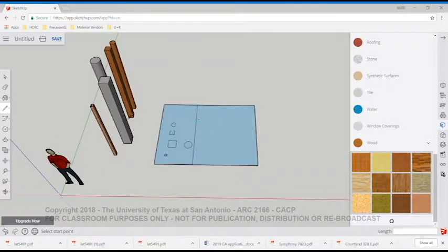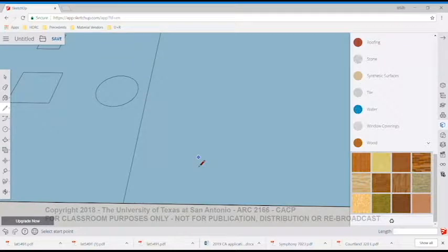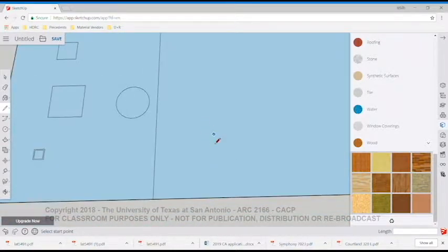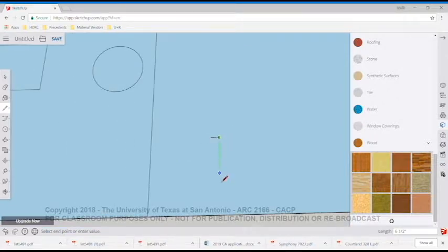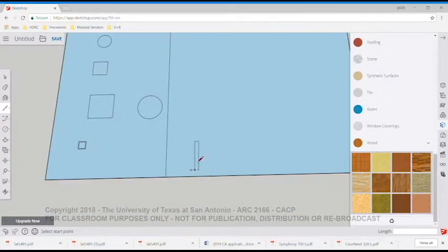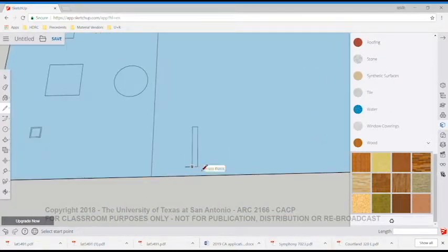So there's a few beam shapes you need to know. We'll start with the simple ones. So if you think about residential construction, you might have a 2 by 12. A 2 by 12 isn't really 2 by 12, it's 1.5 inches by 11 and 1/4 inch. You can do decimal inches in here without a problem. So that would be the profile of a 2 by 12.